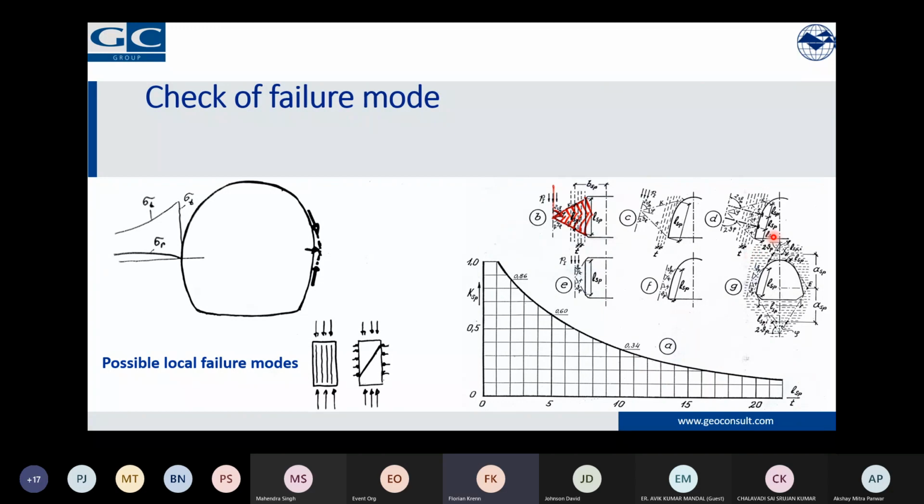And taking something, so to say, a little bit earlier, here you can see the same thing, but with rock bolts inside. Now each of these rock bolts is basically reducing down the buckling length, and just by reducing the buckling length to half, we would end up from 10 to 5, and our strength would nearly double just by keeping that under control. And this is something very important and one of the reasons why rock bolting is so important.